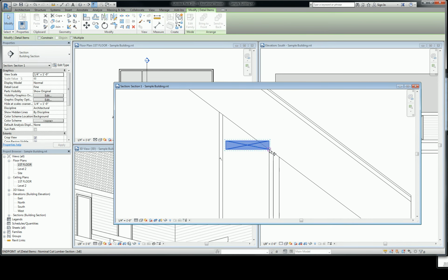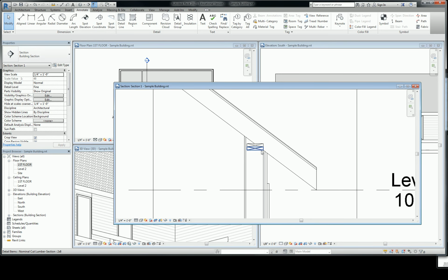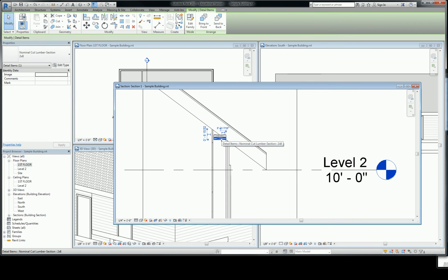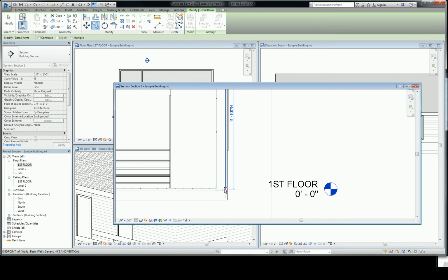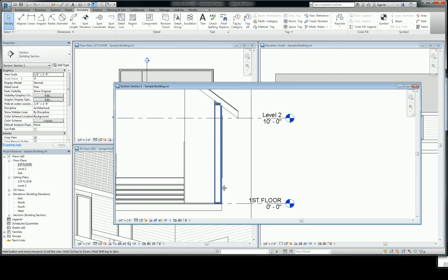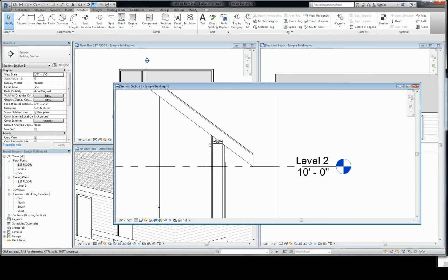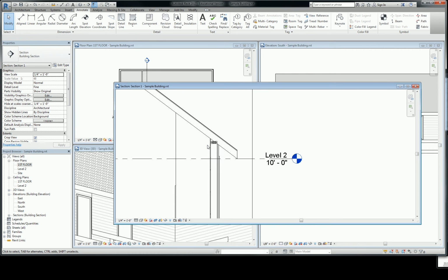So you're going to have double top plates like this, and then that's going to get framed going down the wall down to the base. That's going to be your sill plate. And then those elements are actually just going to be drawn onto your wall section. Okay, that's a very key thing for us to get used to now.